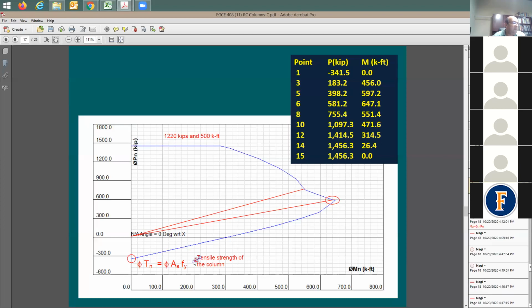Do we have an equation for it? Here's the equation. Have you seen it before? Yes. You have it recorded. And I'd assume that you're gonna be watching this recording before your exam, and you're gonna be thinking here with me. It is not really based on the concrete because concrete is gonna be cracked. So it's gonna be equal to phi factor. How much is the phi factor here? 0.9. Why? Because it is really in tension.